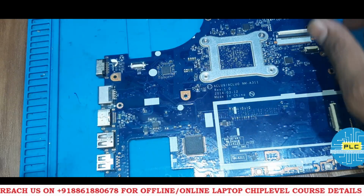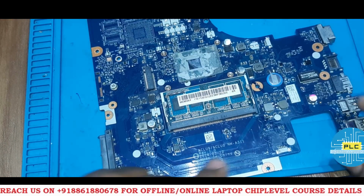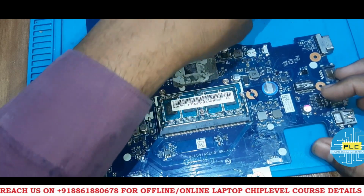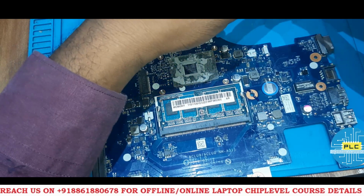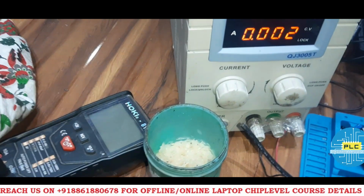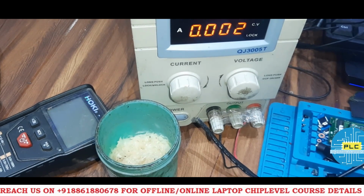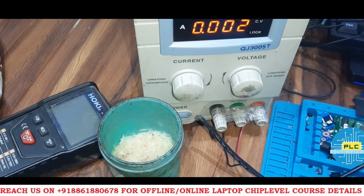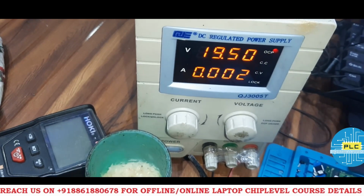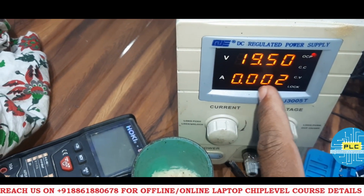Now again one more jumper I will remove. What will be the result we will check. See, here I have removed PJ402. Actually it's the 3 volts always section. Now I'm going to connect the supply. What will be the result we will check. So I connected. Somebody commented to me, he won't believe it's 0.016. Because of only this 3 volts always, we are getting 0.016 amps initially when we connected. See, now it reduced to 0.002.